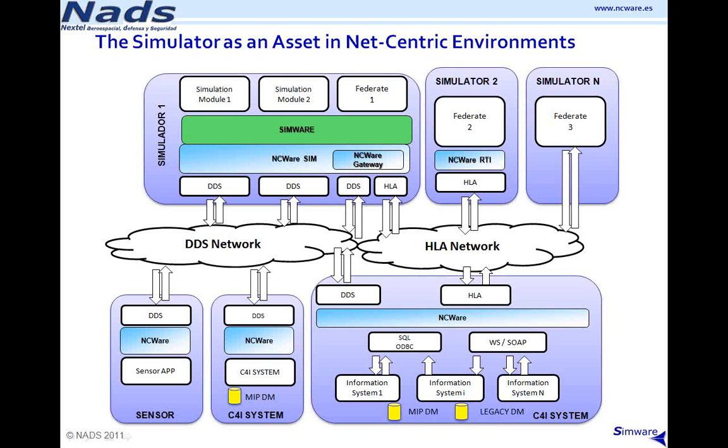Take heed that simulators are not data coupled. DDS guarantees that publishers and subscribers are not dependent on the data model. Publishers and subscribers use the data model, and the data model is shared between them and all the elements of the simulation. Each participant declares its intention of publishing and sends data at any moment. Also, each participant declares its intention of subscribing to some data, and this data can come at any moment. With this schema, the simulator is now one asset that can be plugged or unplugged at any moment, and reused or changed. The weight is in the simulation as a whole, not in the pieces of it.